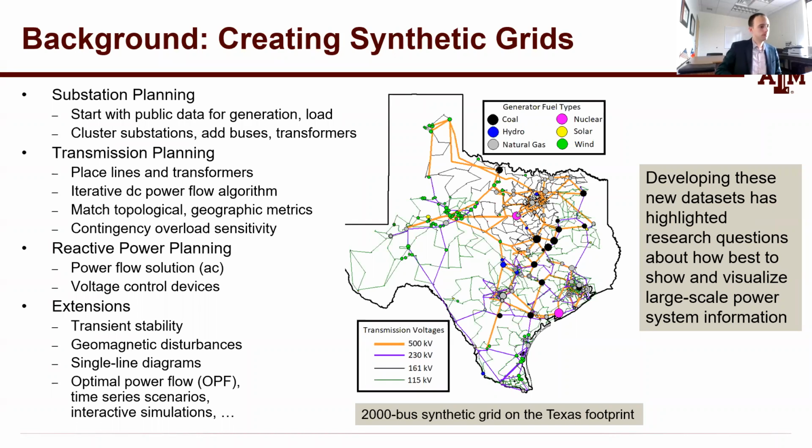And so part of the transmission planning analysis is coming up with metrics that show how the topology matters, and which of the nodes are more important. There's a topological property known as betweenness centrality that shows which nodes are more important. And then the other one, of course, is doing electric simulations, contingency analysis and transient stability runs, and you can see which substations tend to be more crucial to the integrity of the grid.